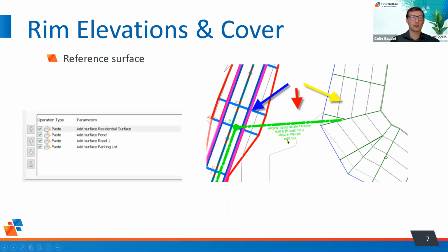As a result, to kind of get around that, we can create composite surfaces. And we can paste in the road surface, the existing surface, and the pond surface all into our 1 finished grade surface and have that ready to go and data referenced into the drawing so that we can then have only 1 surface that we need to check our cover and rim elevations against.